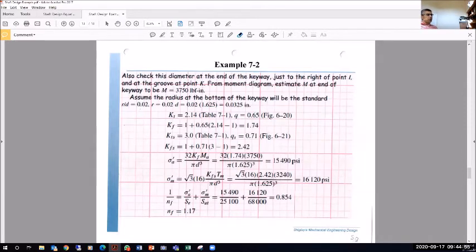And these are based on standard designs. So R over D is 0.02. I do not expect you to know that, but these are standards for keyway designs. So we're learning this from this example. So should you have another keyway, I would use the same standard. So R over D is 0.02, so we can calculate the radius. I find the radius of 0.035.